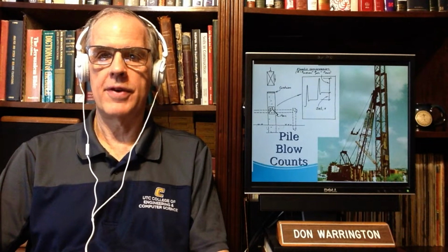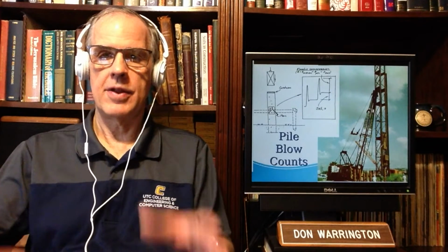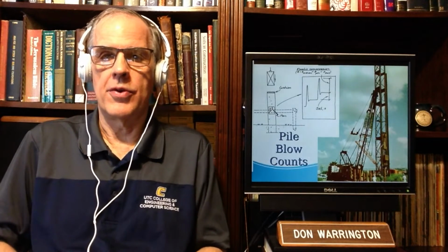Those dynamic effects are largely due to the soil mass itself. We're going to talk about that shortly. But in any event, those are dissipated out into the soil. In oversimplified terms, the elastic energy in the pile and the elastic energy in the soil come back up, and we have a little rebound here.